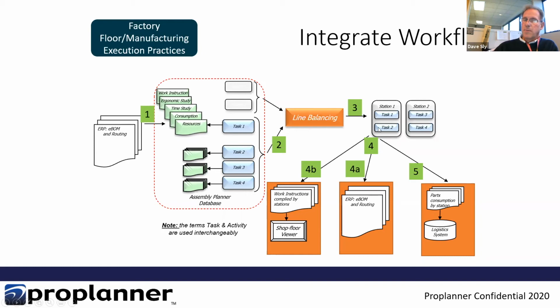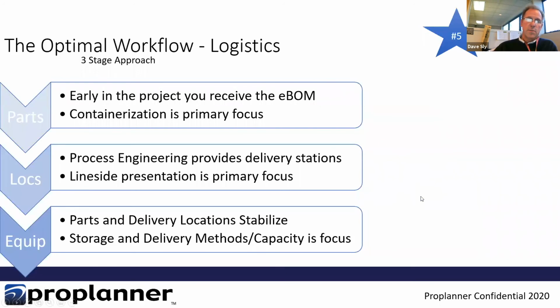Of course, we authored in step 3 many scenarios. Remember the bill of process scenarios, maybe for a 14-person line, a 16-person line, an 18-person line. So I can always go back and republish step 3, changing the configuration of the stations, the tooling and the parts, republishing 4A and 4B, the work instructions and the logistics plans, so they can then be re-executed at an effectivity date, a date in the plant where that new scenario's published version is actually live. Step 5. So you can see how that relationship works.